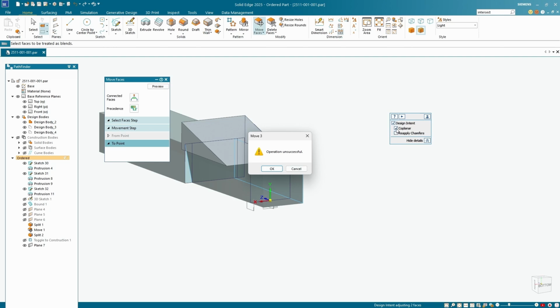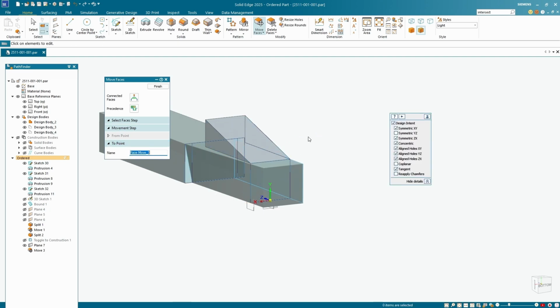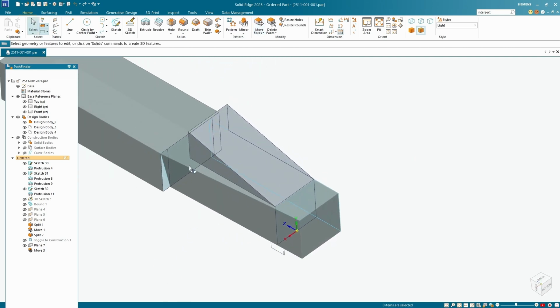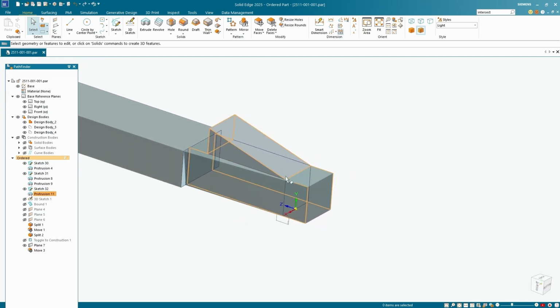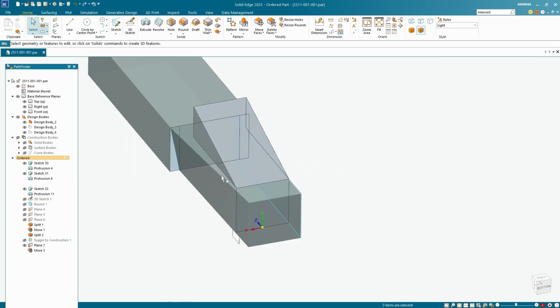Okay, so look, I'm looking at the coplanar design intent. So I'm just going to maybe try disabling that and try that again. Okay, that worked now. So it was the design intent wasn't helping us. So I can click Finish and Cancel, and we have our face there. So I think that's it. That's the basic idea of it anyway.